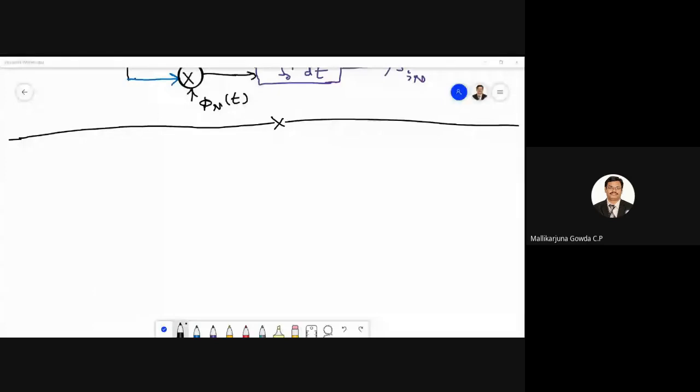And I took the example also. I gave three signals S1, S2, S3, mentioned their coordinate values, and drew how I represent S1, S2, S3. Hope this point is clear. Still people are not able to say what is signal constellation diagram. That n-dimensional Euclidean space is known as the signal space, and the representation of signals in an n-dimensional signal space is known as the signal constellation diagram.